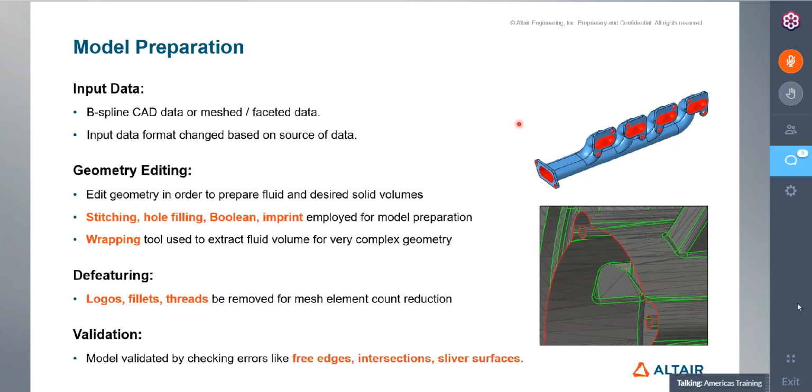Let's say you grab something from one CAD package saved in a certain format, and then you convert that to another format, something like Parasolid, IGES, or STEP, there could be some errors within that, which will cause some geometry bugs, where the geometry will have little imperfections created just out of an error.